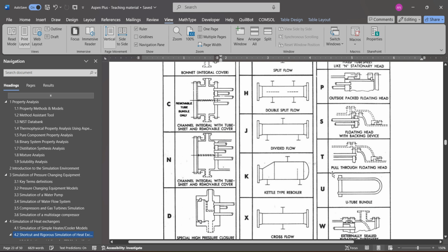Selection of the complete configuration, again, depends on what type of fluids we are trying to deal with, what are the temperature limits, what is the intensity of the thermal expansions inside the heat exchanger, and what should be the pressure drop, because all the stresses have to be accommodated for the heat exchanger geometry as well. And what is the duty of the heat exchanger? For the smaller duties, a single shell pass should be sufficient, but for the larger duties, maybe we need to have multiple shell passes or even multiple tube passes as well.